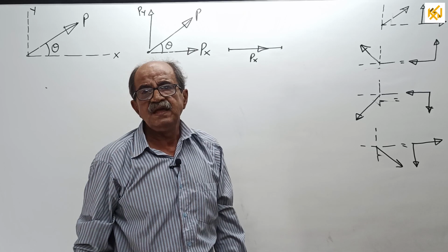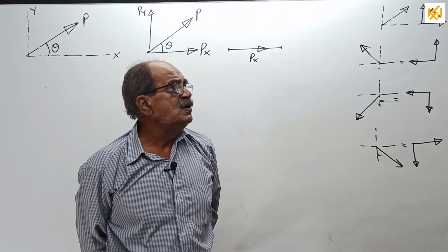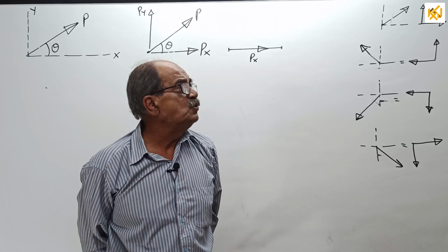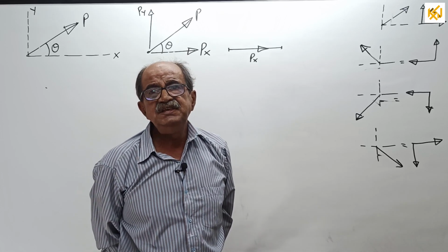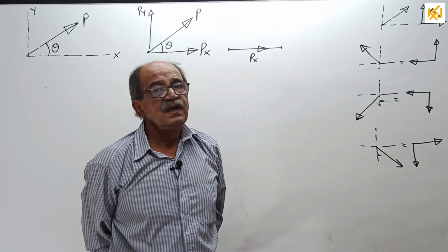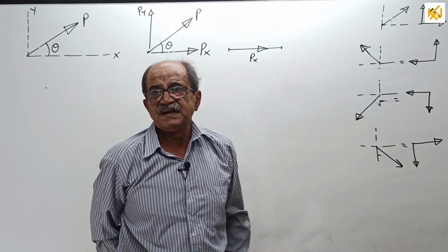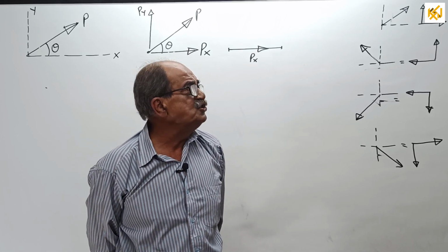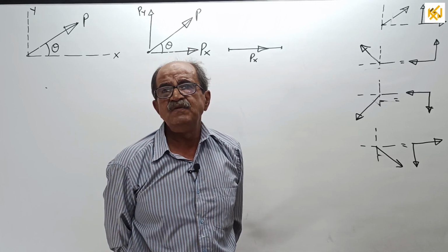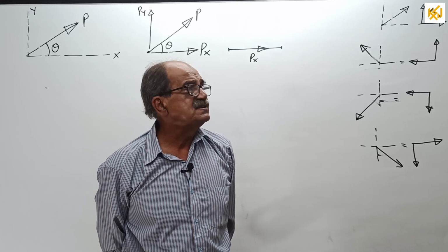I will tell you one more thing. In BMD, when you draw a bending moment diagram in structural analysis, you need the area of the bending moment diagram and you require the CG of the BMD. If you remember, those who have already finished structural analysis, in the moment area method or conjugate beam method, or for finding fixed end moment, in some places you require those areas.